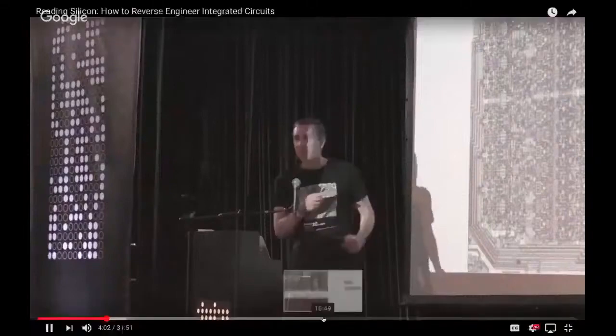Another thing is the Z80 has a couple of instructions that will swap the data in registers. It turns out that it's actually not moving the data between registers. Instead, it swaps the control lines at the top. So it's much faster than actually moving data between registers. Just one of these optimizations that you find inside a chip.